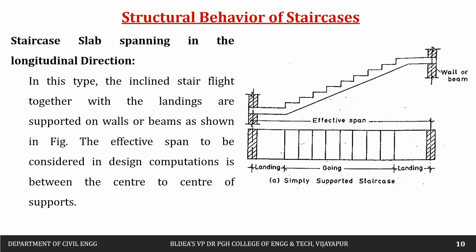So the effective span will be the center to center distance of the support. So this is what we call the effective span. So in this type, the effective span to be considered in the design computation is between the center to center of supports.